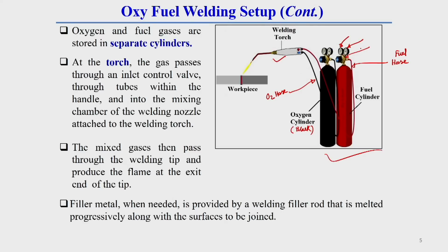For particular types of material, a particular working pressure is required. An expert welder can easily control that working pressure. So, these two indicators represent two different pressures: one is the pressure inside the cylinder, and the other is the pressure applied at the welding torch. If the pressure is within the applicable range, then we can do the welding. If the gas reduces, then the pressure inside the cylinder also reduces. By this, we can use the gases as per our requirement.